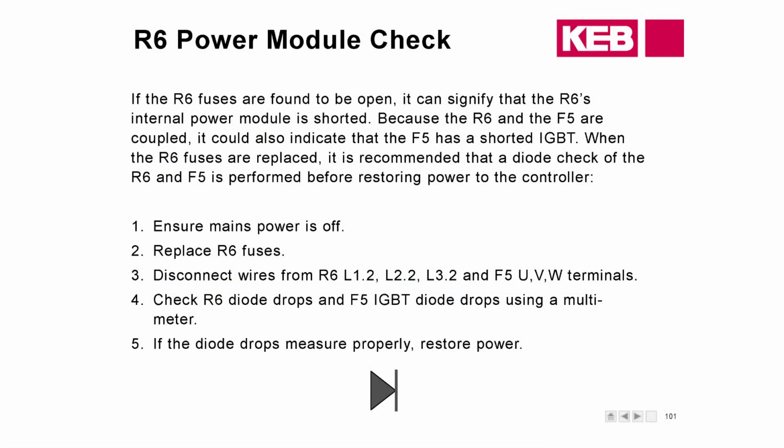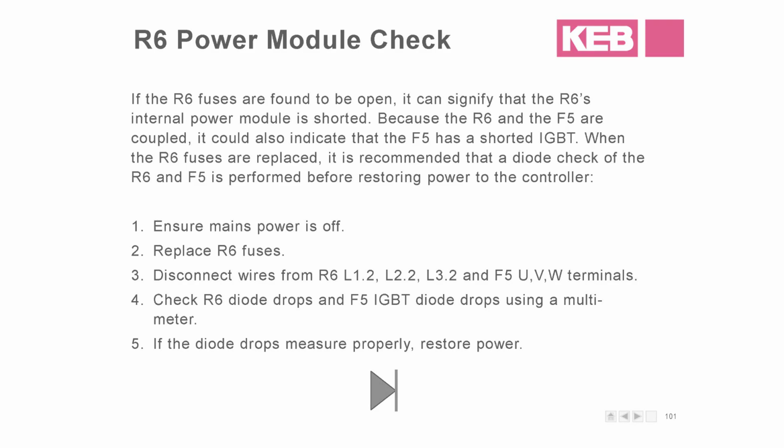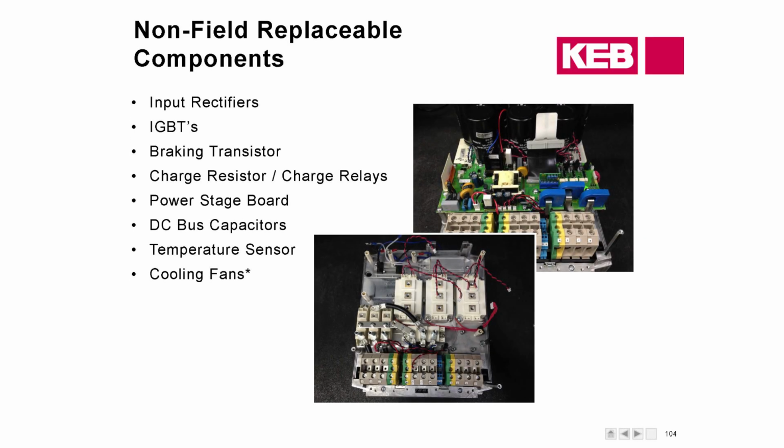This control card here is, again, for the G housing and above. The smaller drives, like the D and E housings, these smaller ones up here, are actually going to have a control card that looks a little bit different. It's going to look narrower. This is an R6 one. The R6 is in an E housing, so it's the same E housing drive, same E housing F5, but it's an R6.